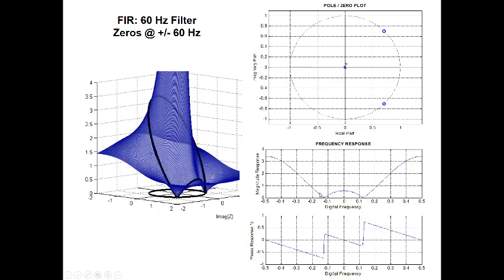But my magnitude response is kind of wonky here. I've got these high wings at above 3 at the Nyquist rate. I'm only coming up to a height of about 0.6 in between. I really would like a uniform notch that has a gain of 1 everywhere, except right there at 60 hertz, and a much narrower notch. This one's way too wide. It's just very slow and sluggish, pulling down the rubber sheet and then rebounding way too much.